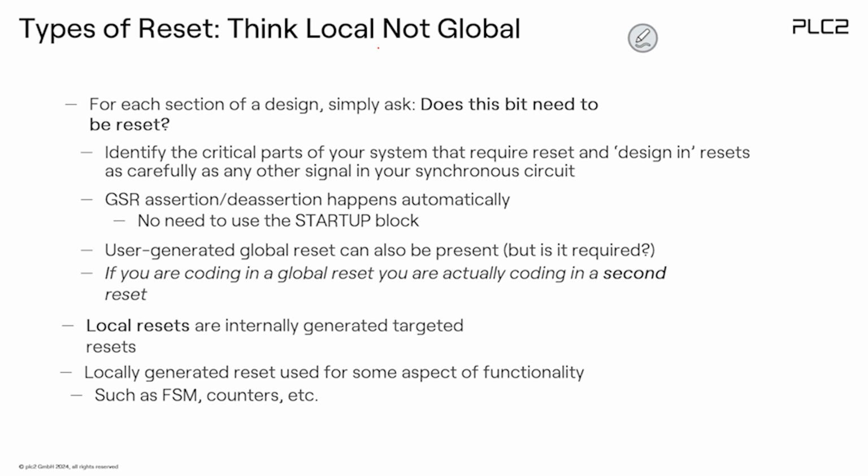For example, for a shift register, it makes not a lot of sense to clear it, because next time you are shifting the data, it's already initialized. So is it really needed? That's always the big question. Also, don't use a global reset connected to all of the registers. Use local resets, because local resets are much easier for the tool to implement.